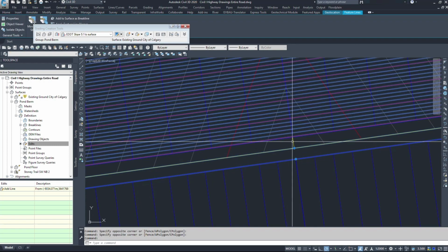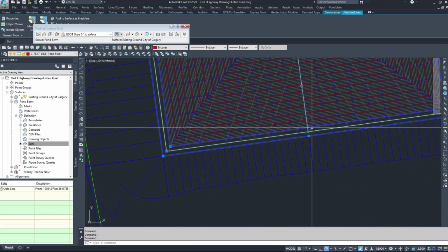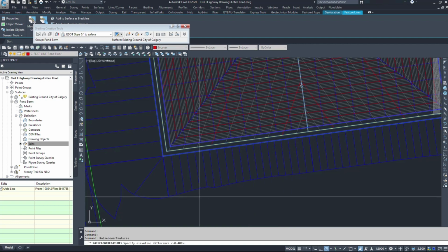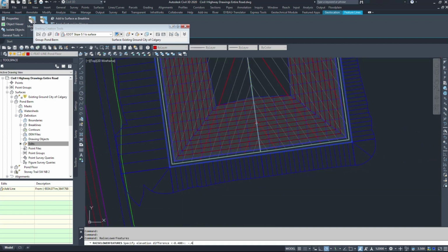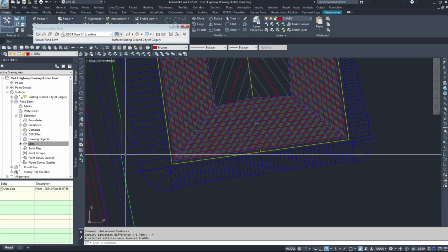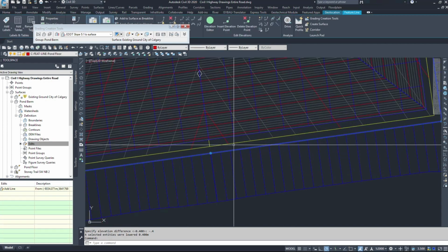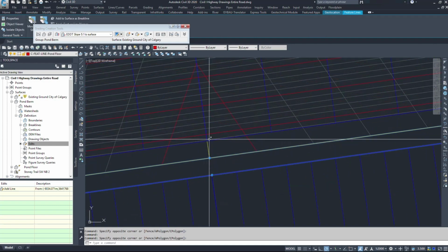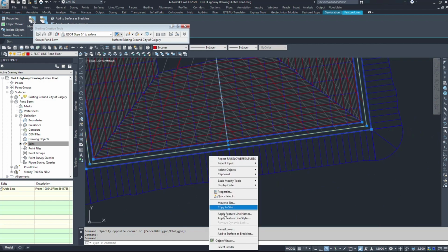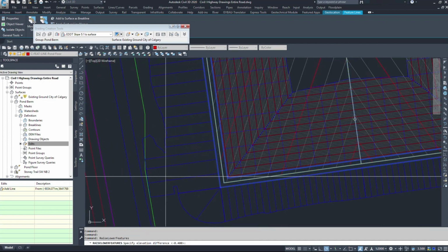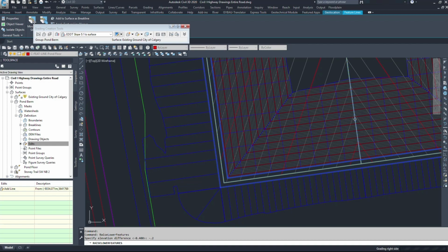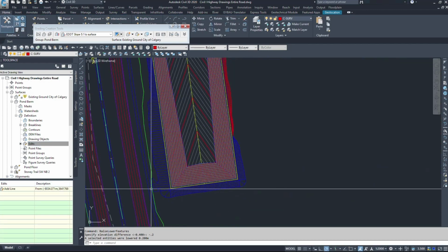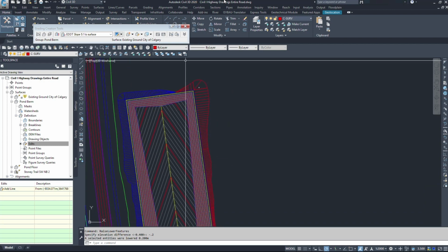Still overlapping. Not my surface. Raise lower. We'll do -0.4 again, and hopefully that is sufficient here. No, still a little bit. Select them all, right click, raise lower, and let's go minus 0.2. So in total, I've dropped it 1.2 meters. I wouldn't type 1.2 off the get-go because you could have crashing issues.